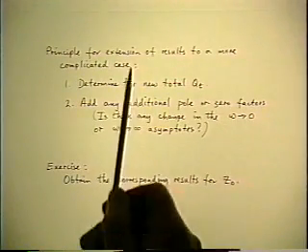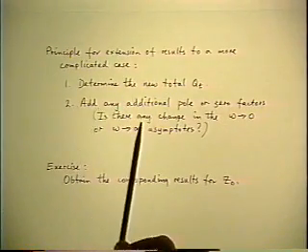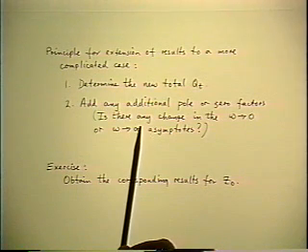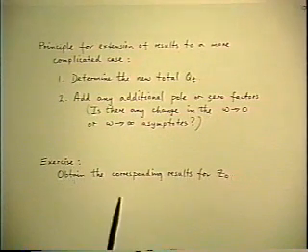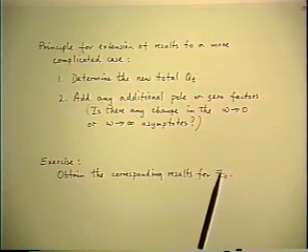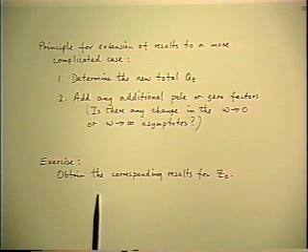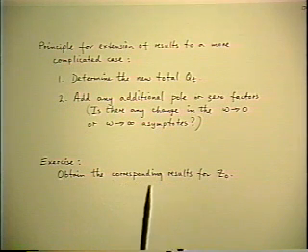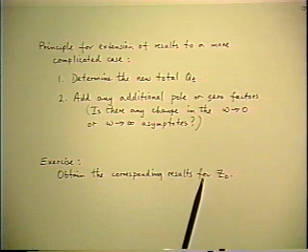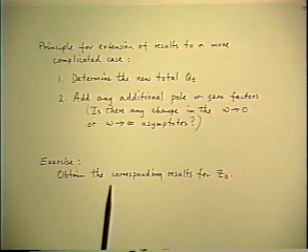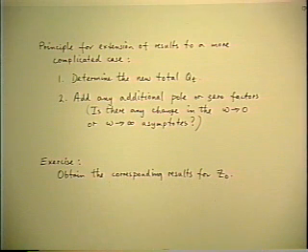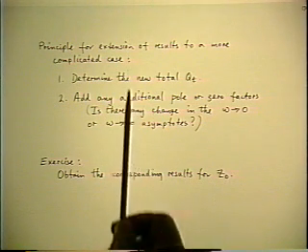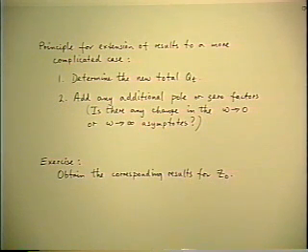So I've written down here the principle that you use in making these arguments to build up more complicated functions. And there's one I didn't do, so I'll leave that again for you to do as an exercise. Build the factored pole zero form quantitatively for the output impedance of the loaded LC filter in the presence of the capacitor ESR, just by following those same arguments.